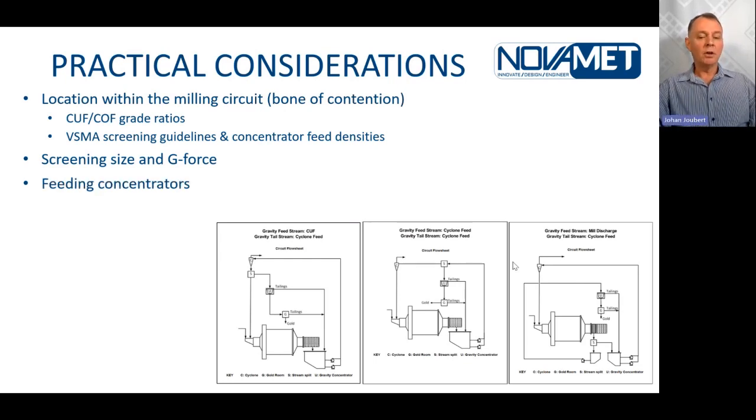Feed to the concentrators is definitely an area where you need to spend a lot of time. These are batch units, so they run between 30 minute to 2-hour cycles and then go to a 3 or 4 minute flush cycle. You need to take these concentrators offline quickly, let them do their flush cycles, and then bring them back online very quickly without starting and stopping additional equipment or upsetting the rest of the circuit. So again, design something that is easy to implement, quick to switch, and does not choke up or cause a potential lockup for gold.